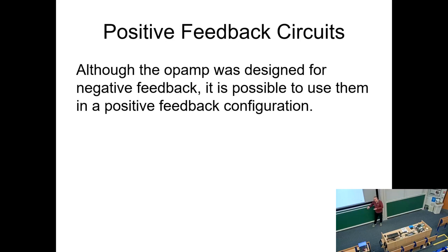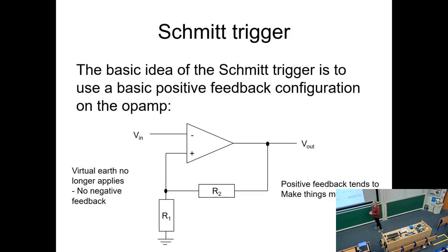Op-amps and comparators are very similar. Comparators are designed to operate with positive feedback, but you can use an op-amp if you really want to. The basic idea of a positive feedback circuit is to use the instability that positive feedback introduces.